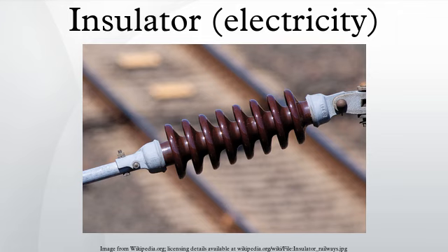All portable or handheld electrical devices are insulated to protect their user from harmful shock. Class 1 insulation requires that the metal body and other exposed metal parts of the device is connected to earth via a grounding wire that is earthed at the main service panel, but only needs basic insulation on the conductors. This equipment needs an extra pin on the power plug for the grounding connection.